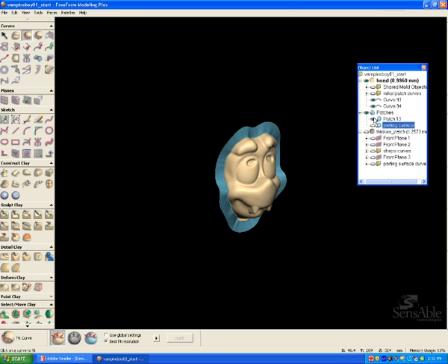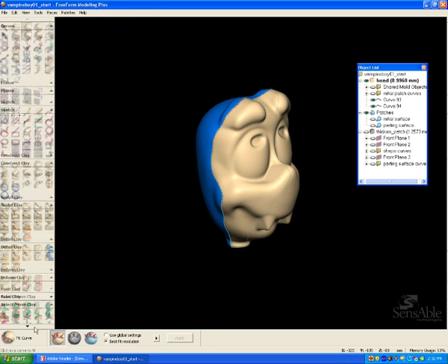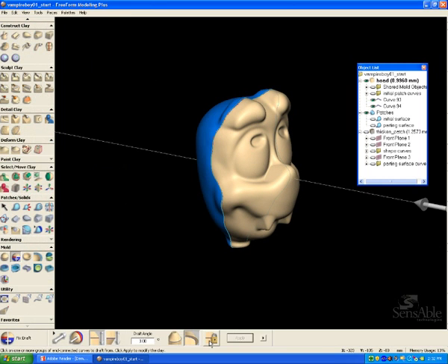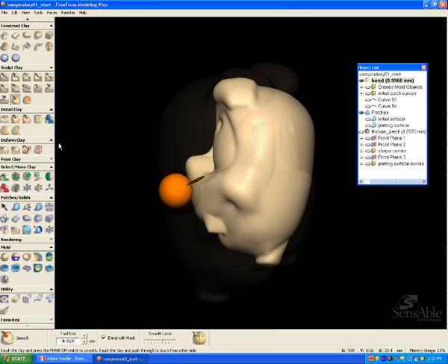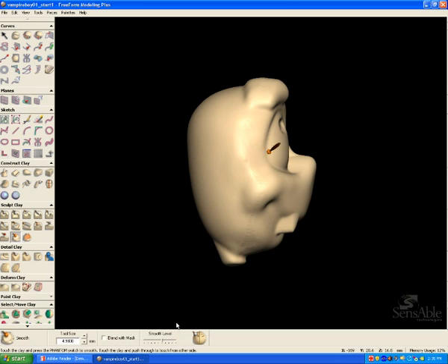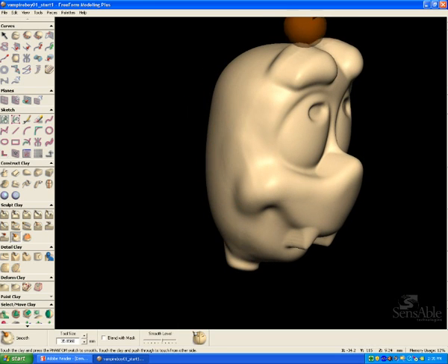It's very similar to the original parting line, but since I want it to be perfectly accurate, I'm going to be using this new parting line instead of the old parting line, because this is the exact intersection between the clay part and the parting surface. So now I'm going to fix the draft one more time just to make sure that it fits perfectly, and I'm going to go in and use my smooth tool and manually just fix up the parting line edge between